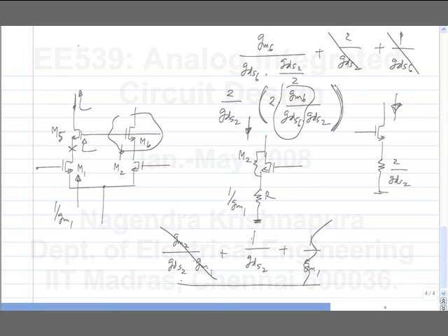Is it okay? It is 2 times the resistance if I had only this cascode. It's exactly like with the differential pair. I look in here and I don't see GDS1, I see GDS1 by 2. Is this okay? Now I do neglect the other terms because they are indeed small compared to this.